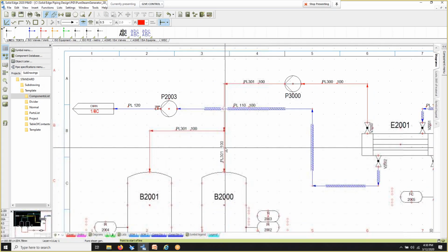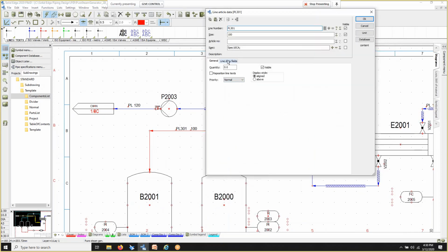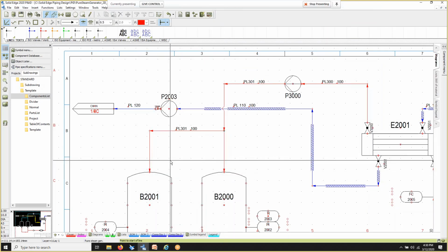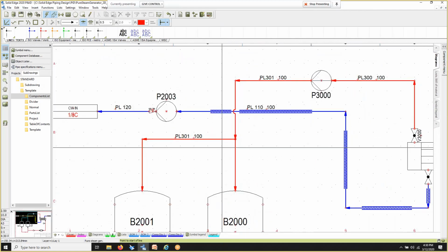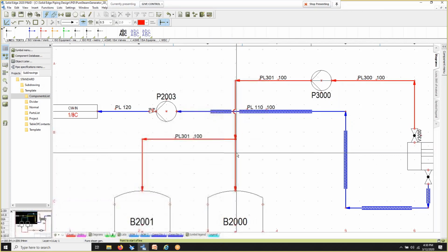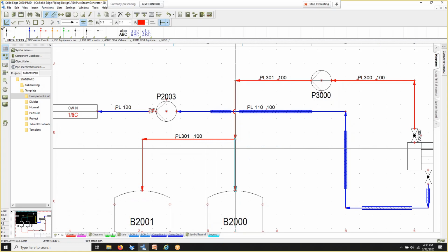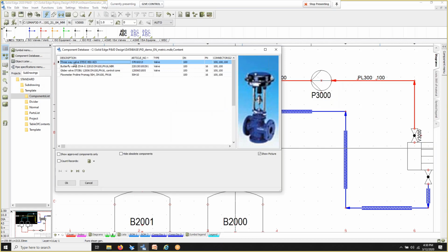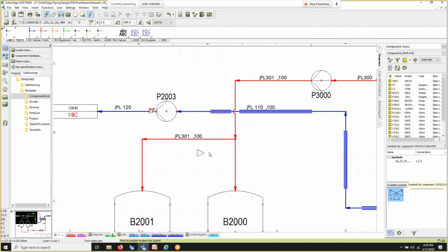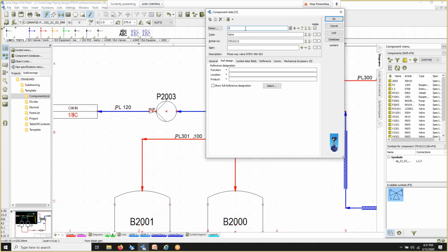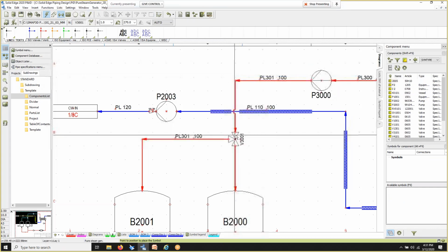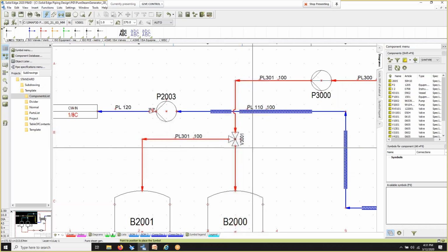Now, if we decide that we don't need that many labels, you can come into one of them and of course, turn those off if we wish. Okay, just to clean it up a little bit as well. Also, working with our pipe specs. Okay, do we want to use a T right here, or maybe we want to get into putting in a three-way valve so we can control a little bit more of this. So again, I can place from specification, and we'll say, do I have one in here? Absolutely, I do. And so we can place this three-way valve in, and then we can place it into our assembly here, and then we could say, let's go with our V3000 and count up. All right, and yeah, notice it trims everything back and cleans it up there for us.